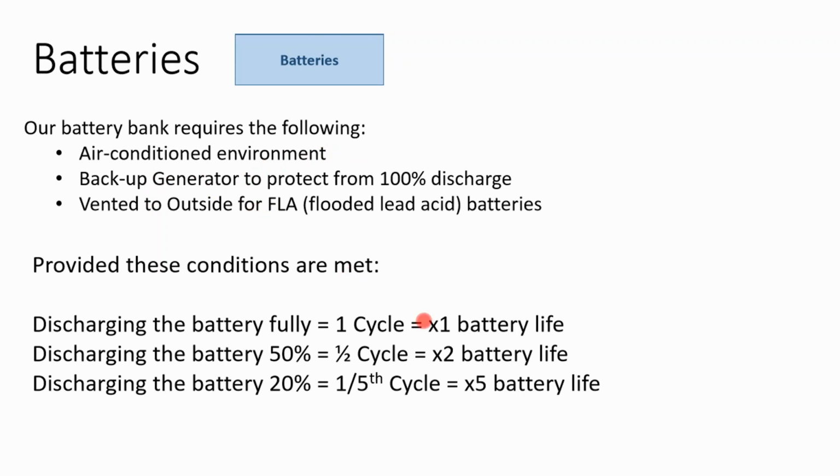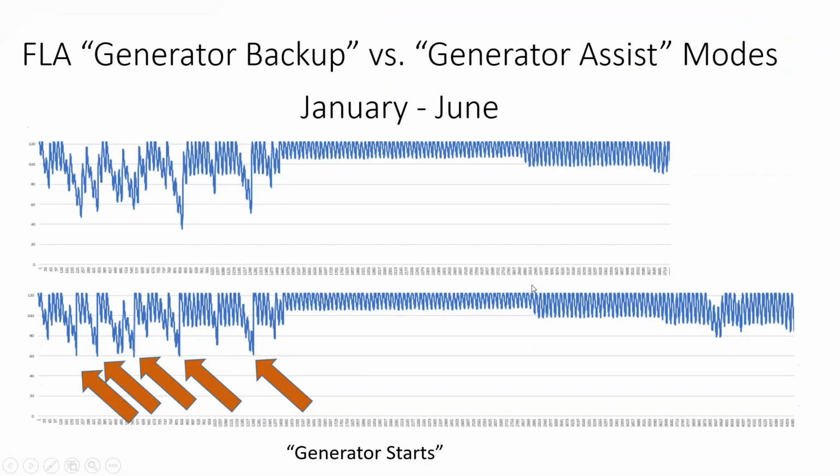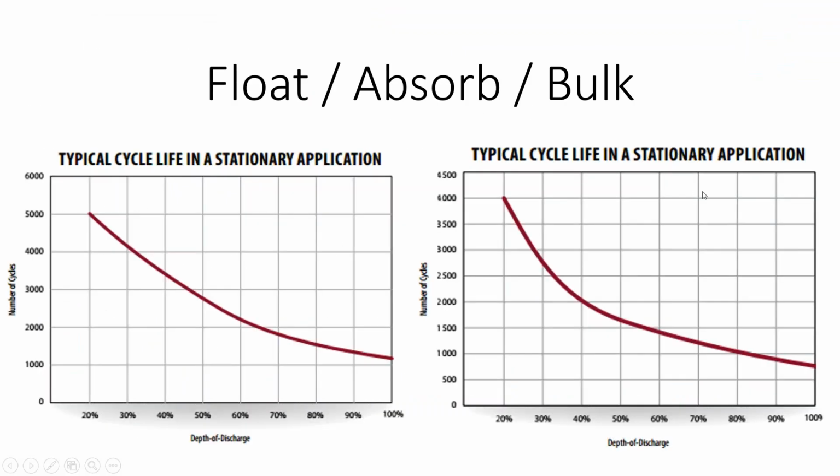And then we really overshot our battery bank size because this was my first system. It's a real house, so we didn't want to undersize it. And the only danger that happens when you oversize a lead acid battery bank is that it lasts longer. So going back to our life cycle charts, it's like instead of doing a 40% depth of discharge at 2,000 cycles, we do a 20% depth of discharge and we get 4,000 cycles.